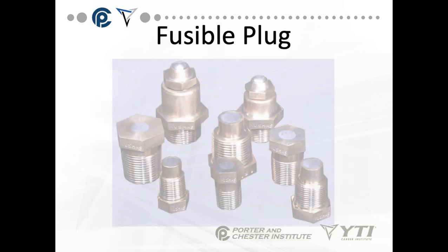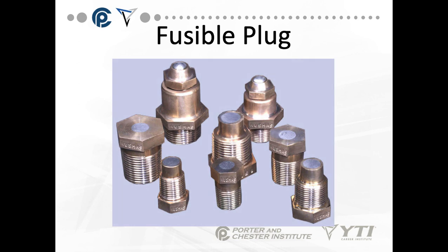Some systems will have a fusible plug in it. This is a pressure relief. In larger refrigeration systems, we use a high pressure relief that's made of a fusible plug. Okay, the inside core of that plug will melt and will blow out under certain high pressure, high temperature. The only way to fix it is basically to replace the plug with a new plug, find the problem, correct it, and then you get to charge it.